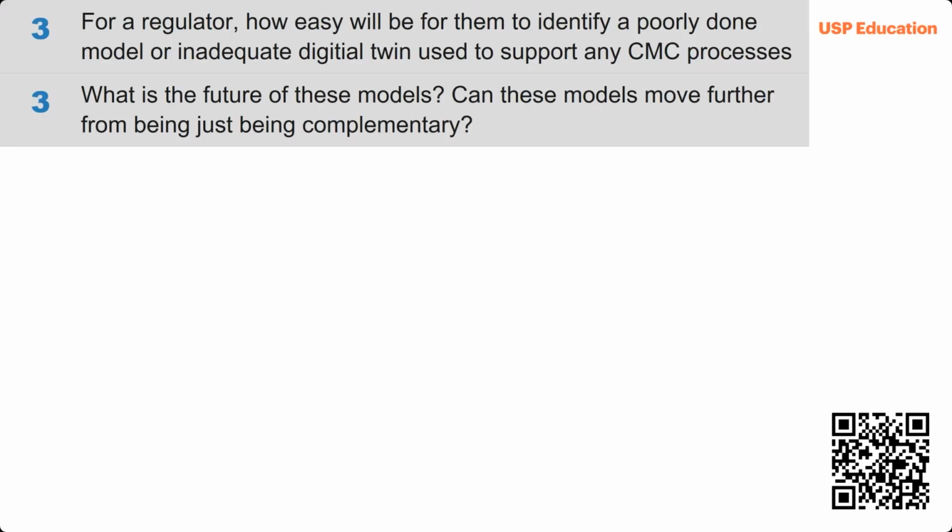Correct. Depending on the application, I had a presentation a month ago at IFPAC where the model, or digital twin, controls the entire process. So the quality of the final product depends on the decisions made by the model. It's a kind of autopilot, model predictive control. For example, if the temperature went up, how can we change the other parameters to stay within the CQA?